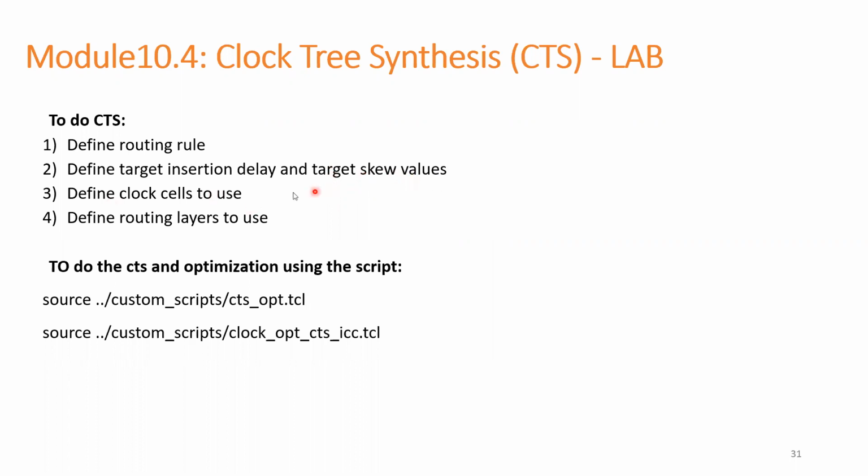Define clock cells to use. There are dedicated clock cells such as clock buffers or clock inverters. These cells will have equal rise and fall times, so with these cells we can achieve the best performance. We need to define the clock cells before starting CTS, so that the tool will pick whatever list we have given.